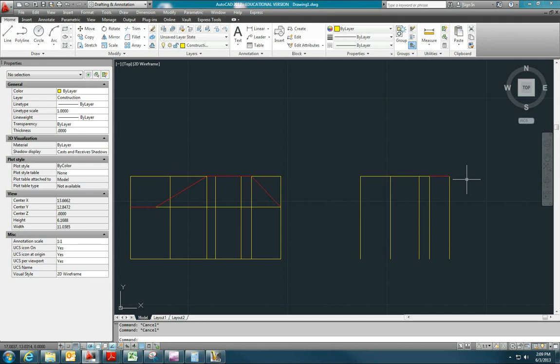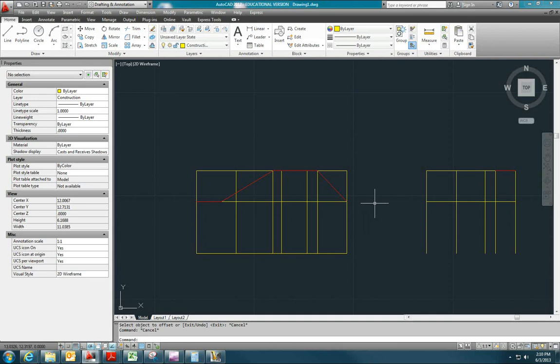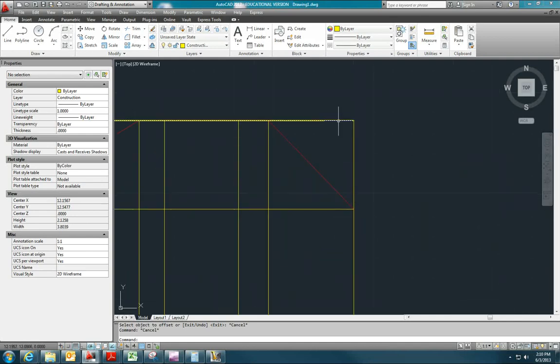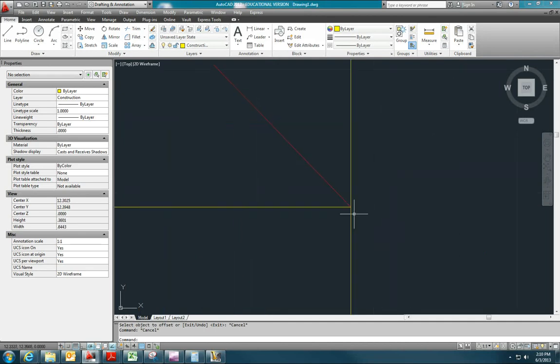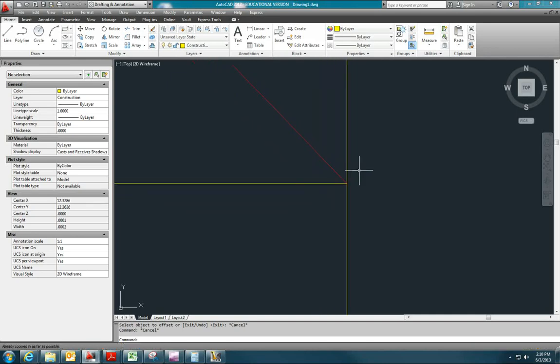What I want to do now is offset the top surface by 0.74. And it also looks like, even though we can't assume this, you remember I offset the same 0.74 down to this level surface here. It actually looks like from here down to the bottom of this line is also 0.74, but let's look just to make sure, because we weren't actually given that measurement directly.